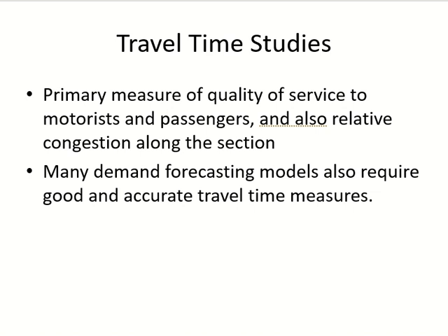So the general trend is the travel time dictates your decision for the demand of the highway. Okay, it's the other way around as well. Sometimes the demand keeps on increasing. When the demand is increasing, what is happening to the travel time? Increasing as well, right? Travel time is also increasing. When the travel time reaches a certain limit, people will no longer go to that highway because now the travel time is too high. Got my point? Okay. So travel time is used.